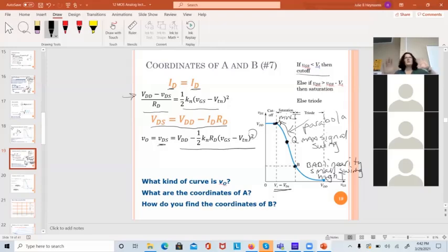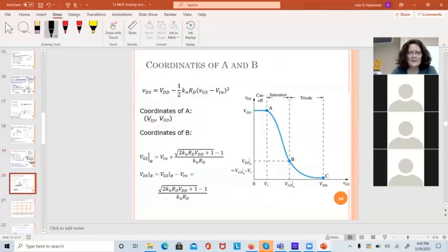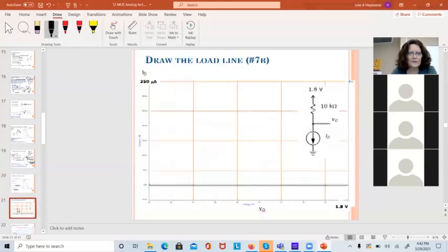If you're trying to build the perfect audio amplifier with the best speakers, you put the Q point in the middle. If you're trying to build an amplifier that works for your cell phone but doesn't drain your battery, you start moving the operating point up this way. If you move it down towards B, it's a mistake. It just doesn't work. Okay, so let's not talk about that.